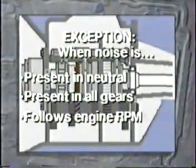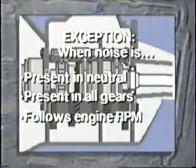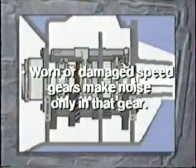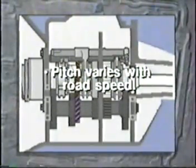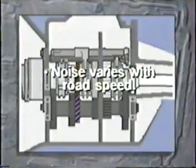If the noise is present in neutral as well as all gears and follows engine RPM, not road speed, the probability is either the bearings or the drive gears are worn. Wear or damage to a speed gear pair will usually make noise only when the transmission is shifted into that gear, and the noise will follow road speed. Except for input shaft drive gears, gear noise is normally affected by the rotational speed and loads on the transmission output shaft. The output shaft bearing is also affected by road rather than engine speed.